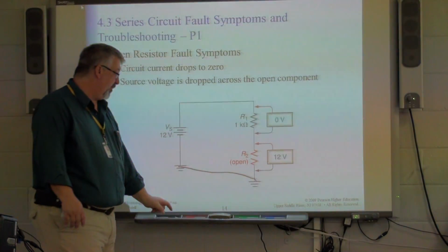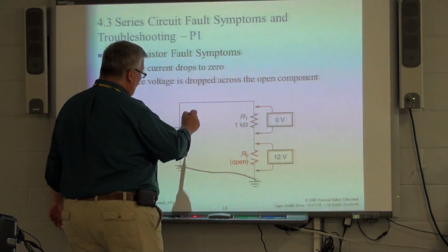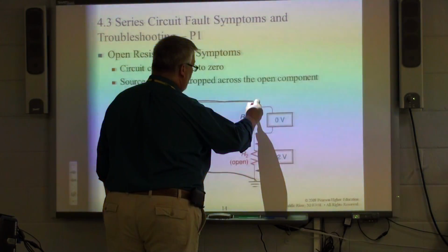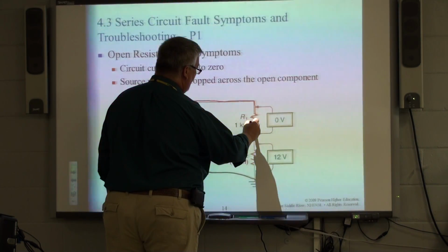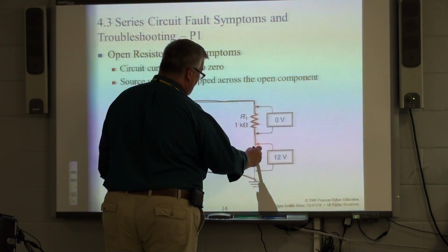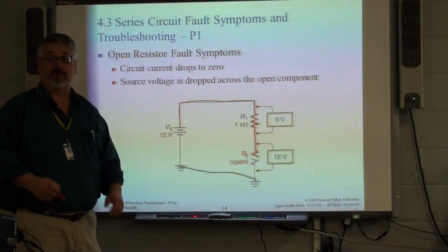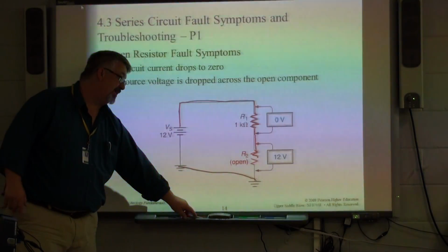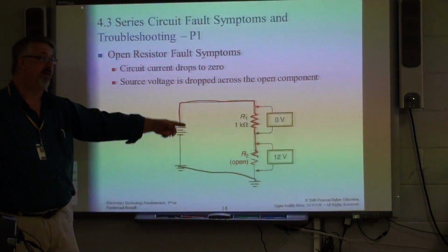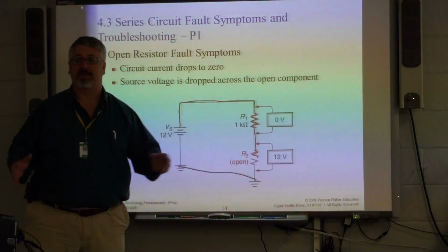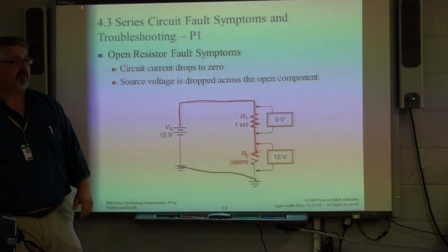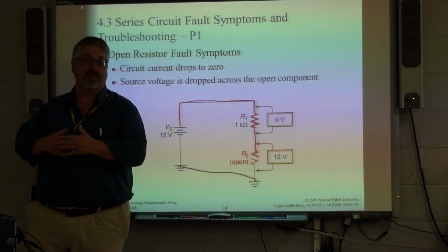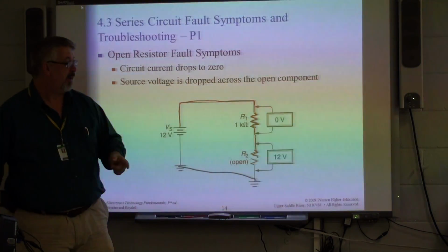So we would normally have a circuit path, whether you start negative, positive, or positive, negative, doesn't matter, of current flowing through R1 and then coming through R2, but it gets right there and there's no path for it. And it can't get back to the negative side, or again, if we started on the negative, we're going to get here and stop. So again, I done told you current's up to you. I don't care which way you go. So we've got an open circuit. It's just like flipping a switch open.